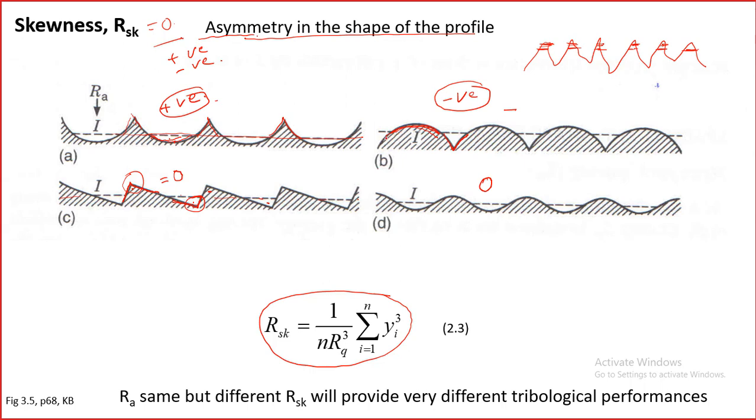So this is how we can physically understand what skewness is. And we can understand that this kind of negative skewness is good for tribology and lubrication, because this provides a flat surface, the contact pressure will be low. Whereas here the contact pressure will be very large. Either this will wear out the softer surface or this itself will break and create wear debris particles. So this surface will give the opportunity for the lubricants to get filled up here, and these lubricants will move to the contact area giving mixed lubrication. So this is all good. So normally our goal should be to find a negative skewness.